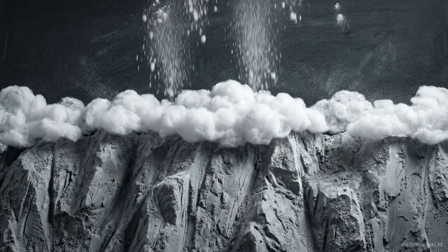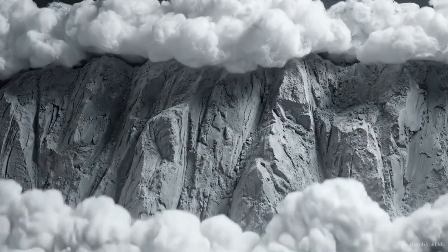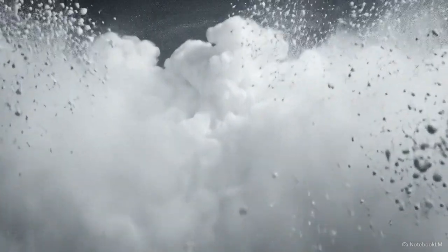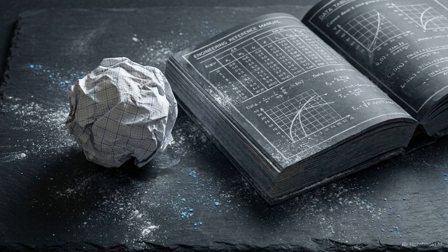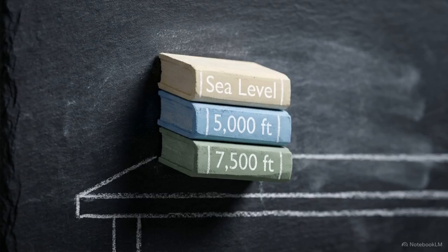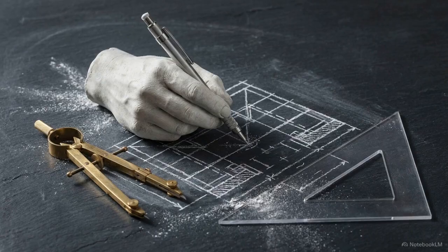As altitude increases, total barometric pressure drops. Because pressure dictates the denominator, dropping atmospheric pressure forces the specific volume of air to expand. This physical reality invalidates standard sea level charts at high elevations. To maintain mathematical accuracy, ASHRAE publishes entirely separate charts calibrated specifically for altitudes of 5,000 and 7,500 feet. The specific volume lines anchor this two-dimensional chart in physical three-dimensional space, forcing the mathematical model to account for geographic altitude and atmospheric density. We have deconstructed the static properties.